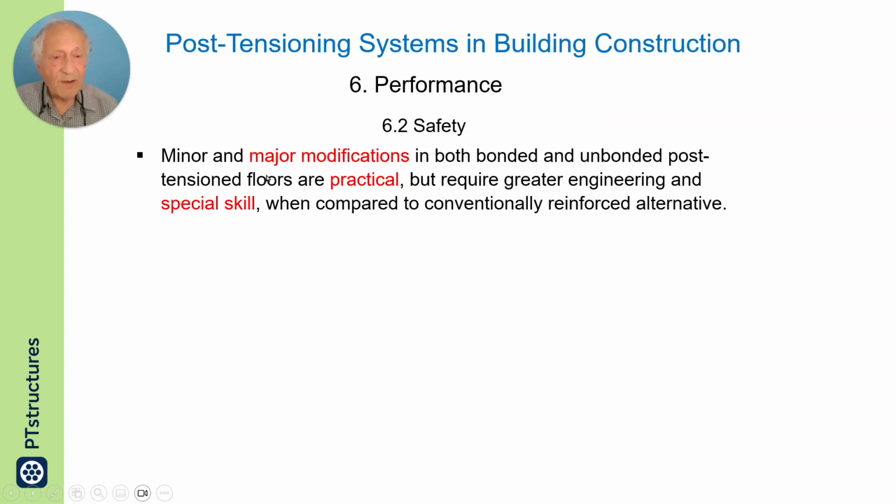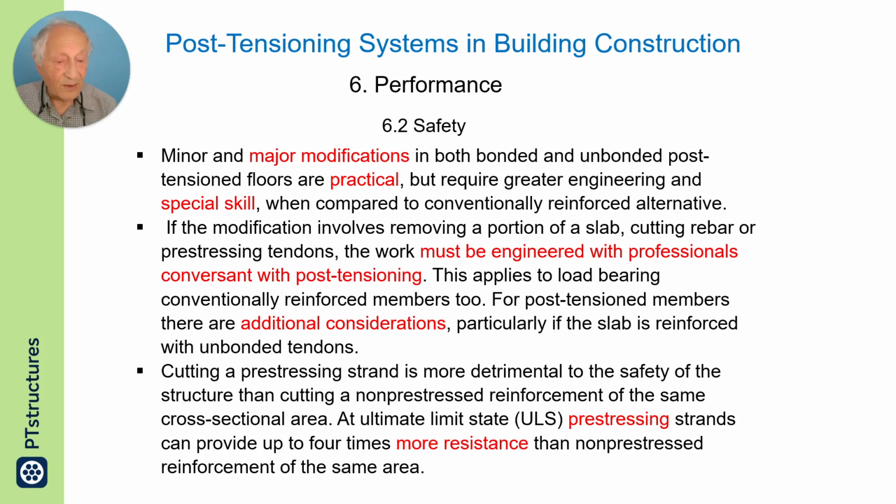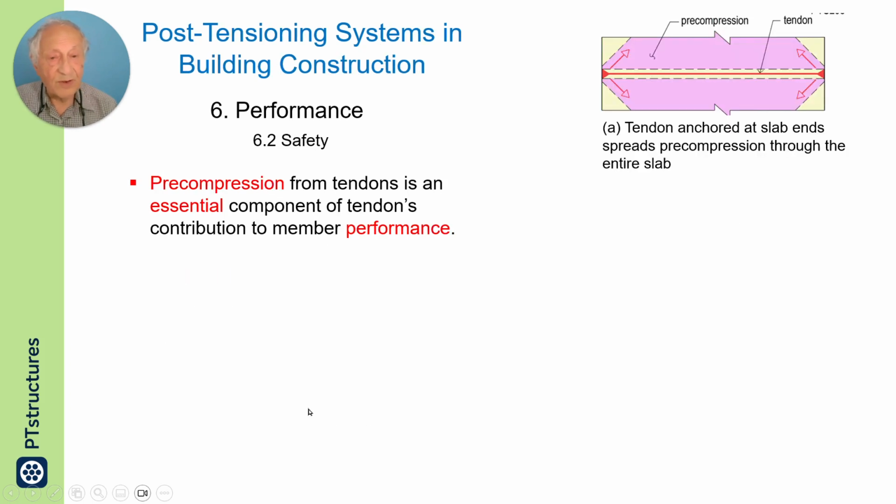So it is possible. It is practical, but it requires special skill, and is a little bit more complex. It must be engineered with professionals conversant with post-tensioning. There are additional, obviously, considerations because of the force in the strand. Now, cutting pre-stressing strand is more detrimental to the safety of the structure than cutting a non-pre-stressed reinforcement of the same cross-sectional area, because at ultimate limit state, the pre-stressing strands provide 4 times more resistance than a rebar of the same cross-sectional area.